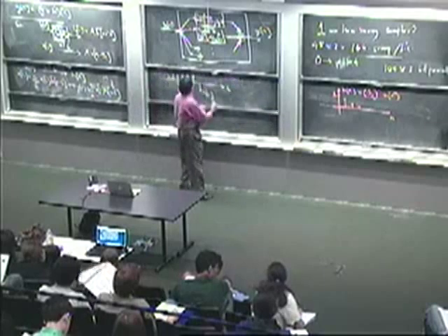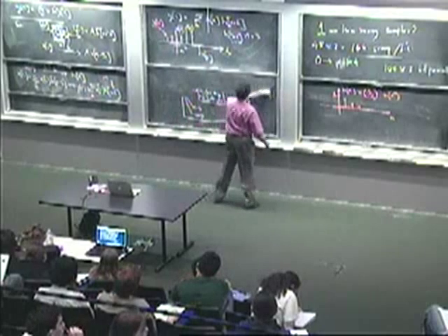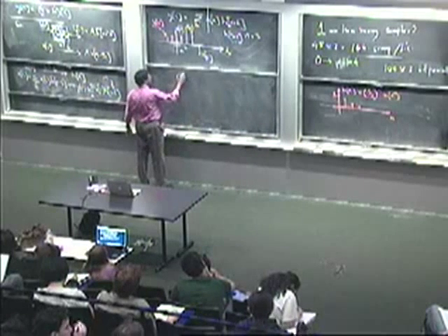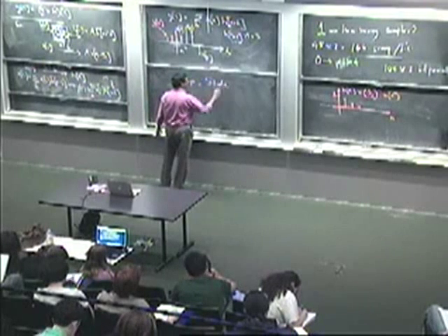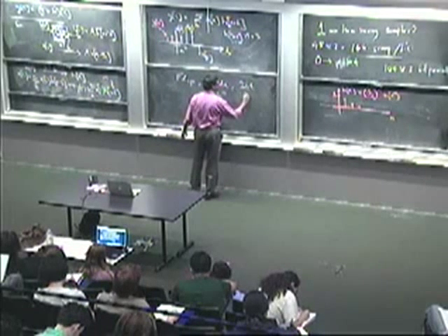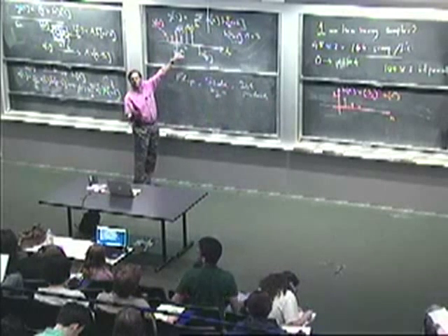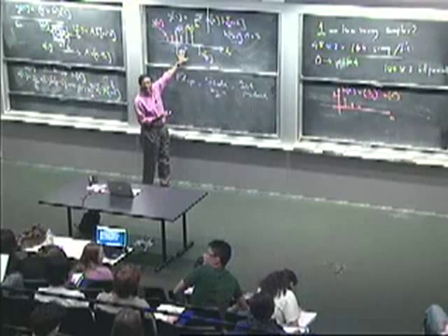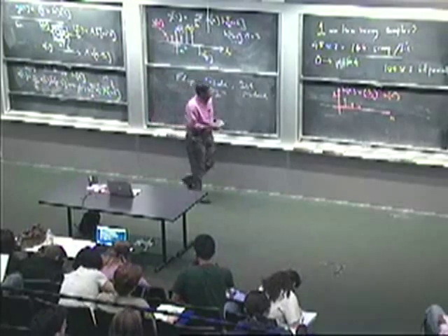All right, so in recitation tomorrow, you'll get practice on this. What you want to think of, sort of the mantra for graphical implementation of convolution, is you've got to do the flip of one of the time functions, slide by n, and then the dot product. So you slide it to get one particular value of n. If you want the next value of n, you slide it one over and go through this whole thing. So it's flipping, sliding by the right number of spots, doing the inner product. That gives you one value of the answer. And then you repeat. All right, you'll get more practice in recitation.